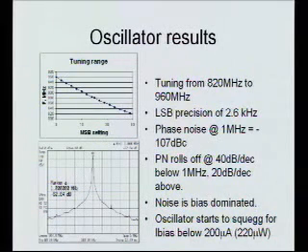Phase noise is way worse than I modeled. We haven't talked about it yet, but let this be a lesson. You can do great phase noise simulations and not remember to include bias and be completely messed up later. So bias got me. I was able to help it some in a second round of design, but it was the limit on the design in the end.